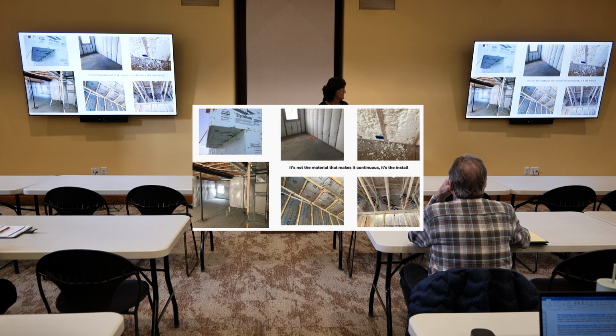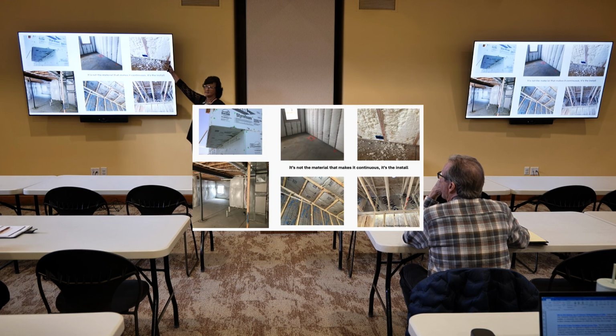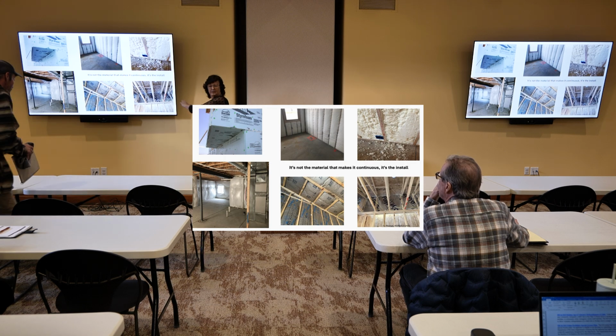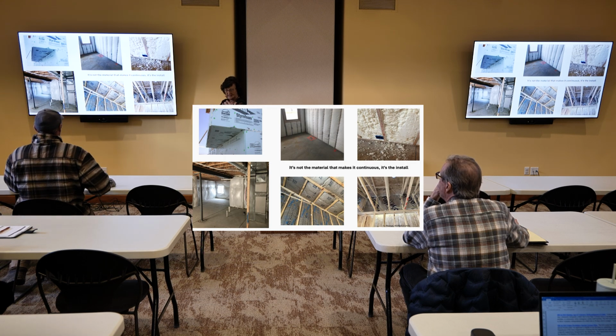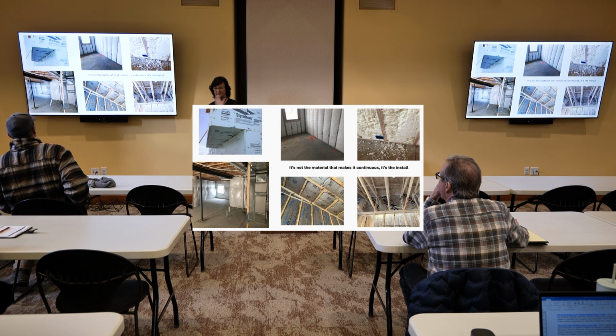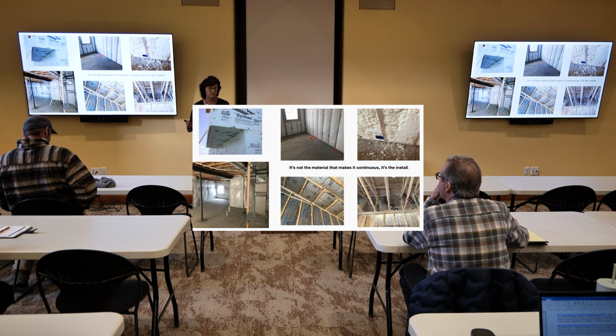I will say it's really hard to get a continuous insulation in a spray foam, right? Because no matter where you're spraying it, there's some framing, and you're going to have to go over that framing with the same thickness as in the cavity to get that R value to make it be continuous. Who's going to do that?